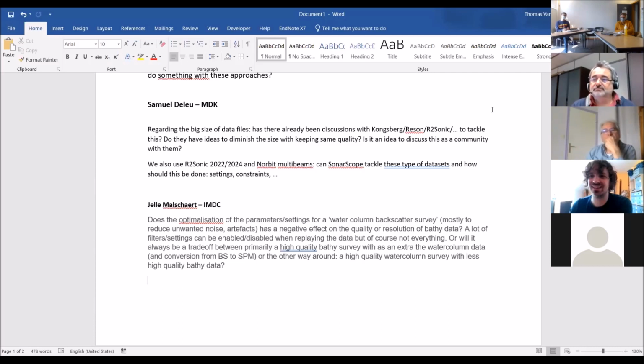And I think preferably you have a ping rate for the bathymetry and a ping rate for the water column data. That if you do a survey, you can say bathymetry, let's say full on, full force, everything, and then every 5th or every 10th ping, I want the information on the water column data as well.